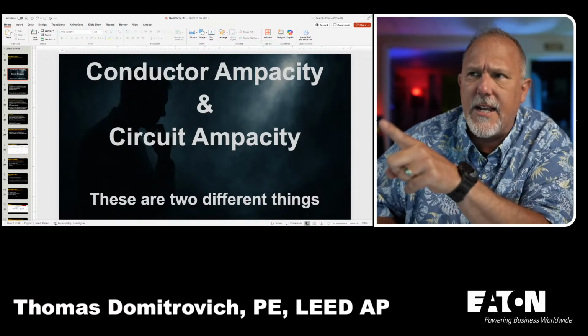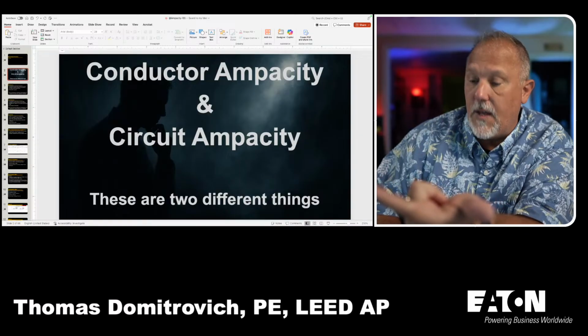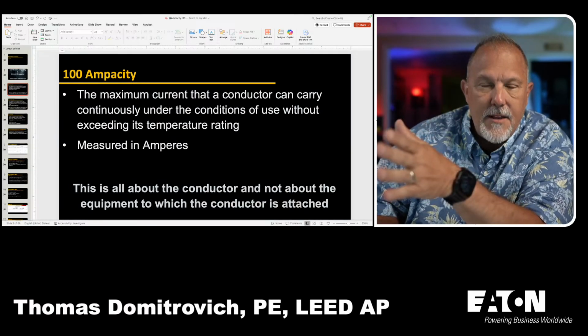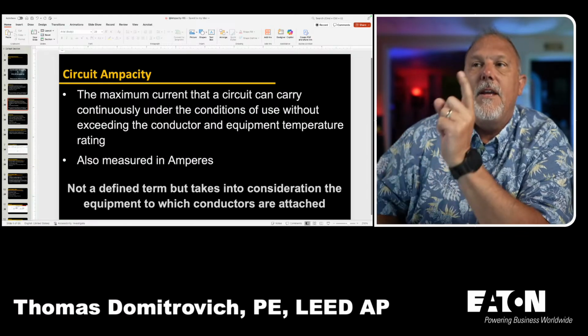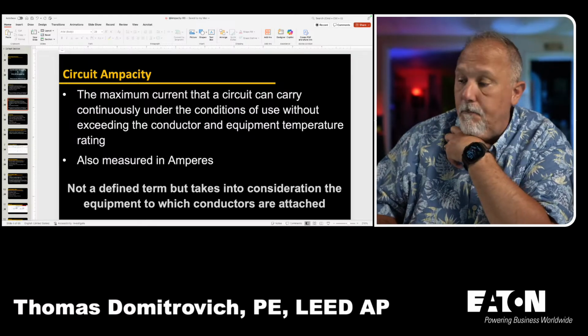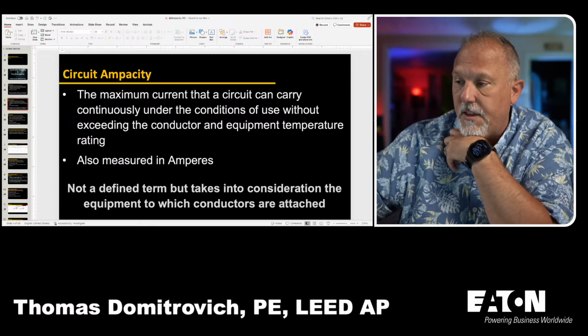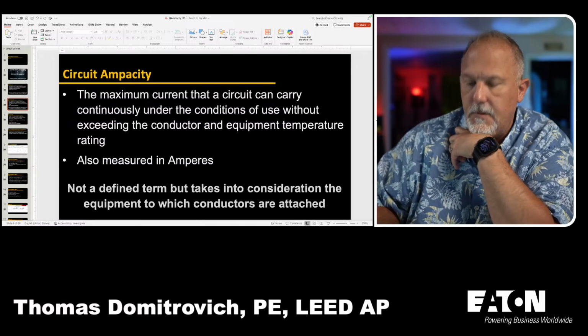let me try to understand what you're saying. I have a conductor ampacity and I have a circuit ampacity, and they're two different things. Conductor ampacity is out of the definition from the National Electrical Code. Circuit ampacity is not defined in the National Electrical Code, but I'm making it up and sharing that with everybody here. All right.